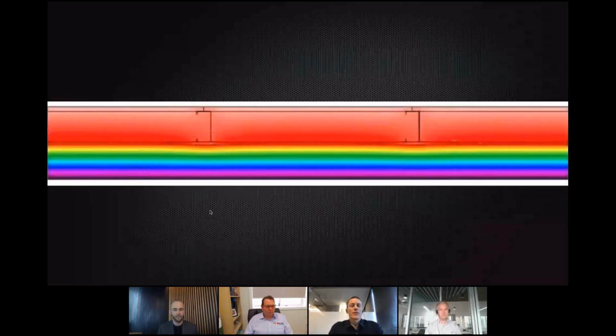And so the best answer, as Alex has shown, is to put all of the insulation outside the line of framing. At this point, the lines of temperature in this image remain parallel. At this point also, the framing material becomes irrelevant. So it could be CLT, it could be precast concrete, it could be steel. So now we have to attach cladding structurally outside this insulation. And it's at this point that it's really easy to start destroying all of our good work.